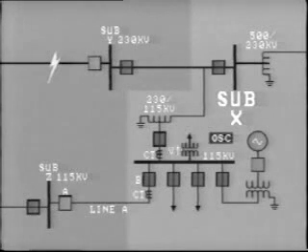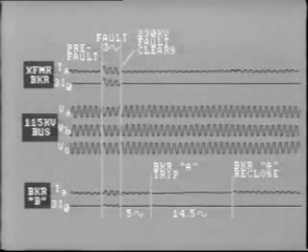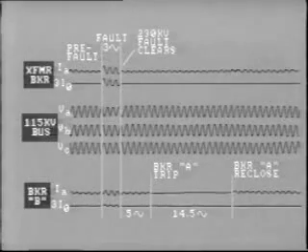Also monitored are the 115 kV bus voltages in all 3 phases, as well as A-phase and residual current for breaker B connecting to substation Z. You can see the onset of a single line-to-ground fault on the 230 kV line.